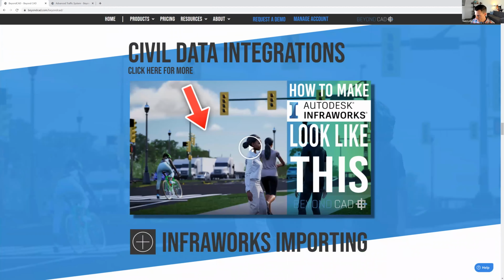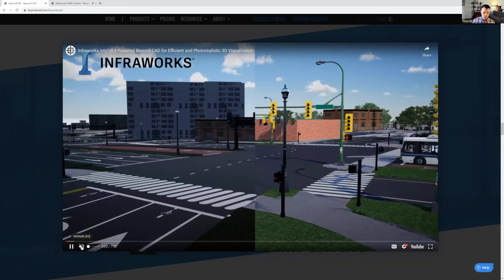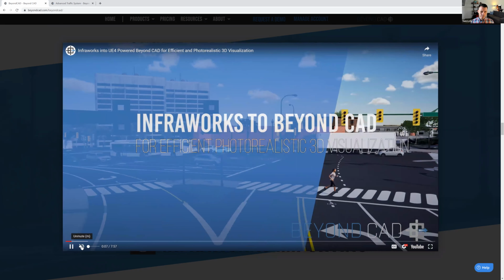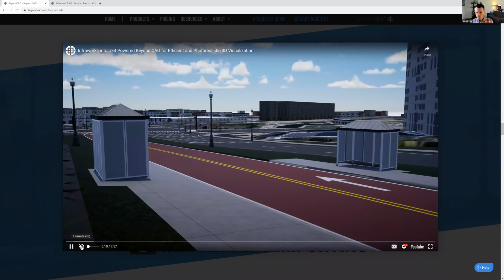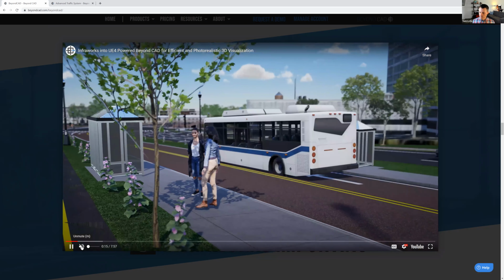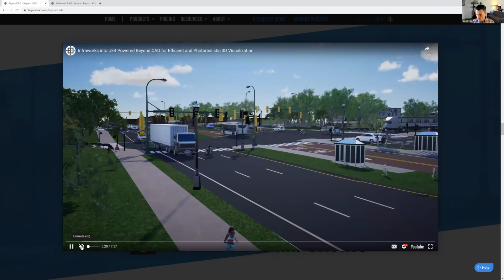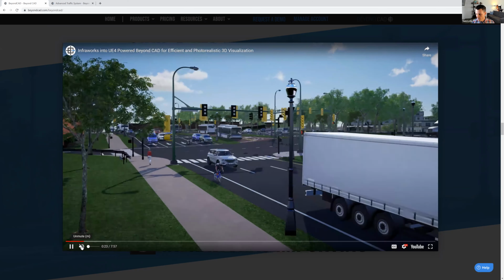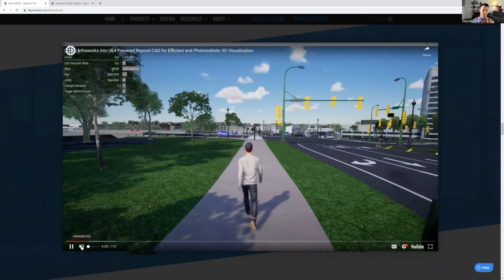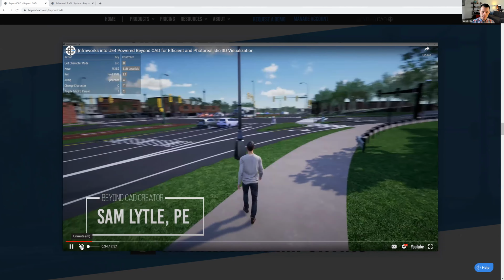And I actually just released this video, I think it was last week, and you can go check it out on our website or on our YouTube channel. But that seems to be the most efficient way because not only can you do more things in Infraworks, like adding terrain and buildings and more things in the background, but it also comes into BeyondCAD really well. And then you can apply textures, you can apply the traffic very quickly, including the pedestrians and cyclists. You can set up your cameras. So that's the preferred workflow right now, bringing it through Infraworks. And hopefully within the next month or two, we're going to have direct DWG support as well.